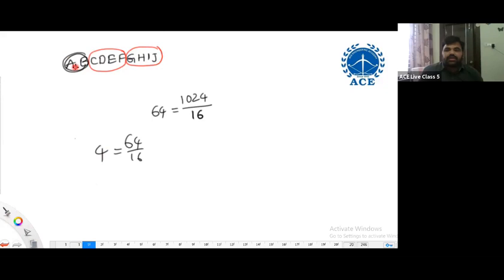Only 2 inputs remain, and these 2 should be used as inputs. Optimally a 2 to 4 decoder is required, but here I use only a 4 to 16 decoder. In that I want to use only 2 inputs. Then how can it be constructed?